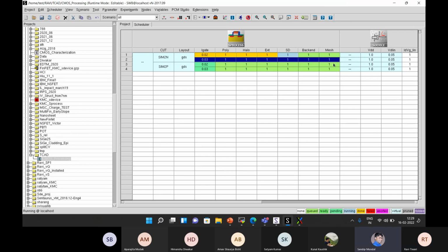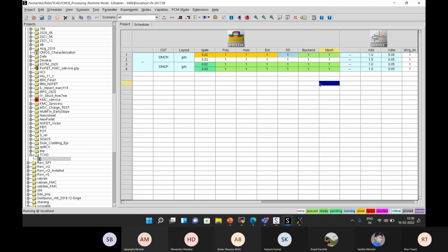So, for example, if you have a capacitor with an oxide thickness of 10 nanometer, you can use a maximum of 3 volt to 5 volt. Now if you use 30 volt, which is always used for, let's say, 100 nanometer thick oxide, then the capacitor will automatically be damaged, right?